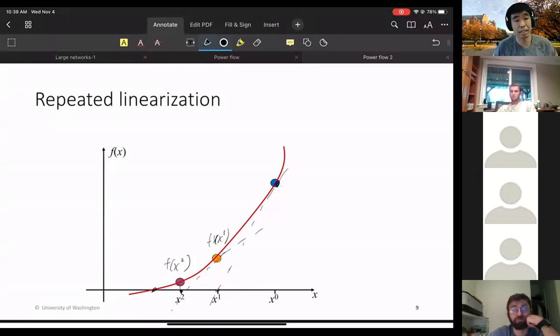Actually, let's look at that. Whether this thing converges or not depends on your first guess, right? Because once you do the first guess, everything else is determined. Once you guess the first thing, then you have a sequence. It turns out for power system equations, most times you need to guess an initial v and theta. Your random guess will be v equals 1, theta equals 0. That's a so-called flat start. So that will be your random guess. Again, 95% of the time, that random guess works. 5% it doesn't work. And really, that 5% causes a lot of headaches for us.